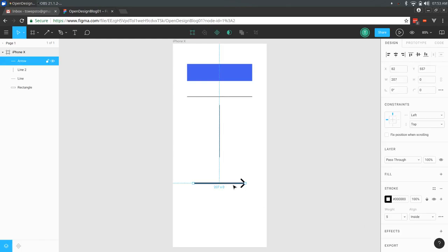So to move stuff around, I showed you the click and drag. Another way that I like is holding down shift and using the arrow keys, and it'll give you alignment tools. So shift and arrow moves it a big increment, and then just the arrow tool moves it a very small increment. And you saw that line show up still while I was pressing this key. It does an auto alignment even if you're pressing the key, which is really powerful.